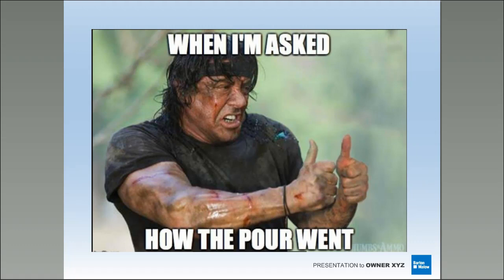Typically, on a curled slab, if I know there's a lot of curl there and I'm trying to avoid aggregate, I'm probably going to go after it on my hands and knees with a hand grinder. Because if I've got a good grind guy on the edge, he's going to be more experienced with it and not cut right into it and expose a bunch of aggregate. I hope that helps in what you're looking for, Mike.